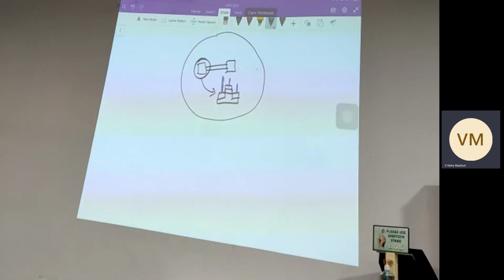So a metal coming out from gate, drain, source. These are nothing but some metals, right? Interconnects, which got connected below, right? And they came out as a strip. Now these wires or interconnects are connected to something called pads or pins.